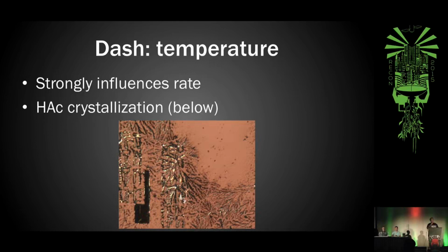And this becomes a real problem because if it's not a hot day, this will actually precipitate, cover your die, and actually interfere with the reaction. So the way that I get around this is actually to use a heat gun, just like I was using for maybe decapping or some of the delayering work, and just run it at a slightly elevated controlled temperature so that regardless of whether I run this in summer or winter, I get kind of a repeatable process running at about the same temperature. And below you can see an example of what this looks like when you do it at too cold of a temperature.